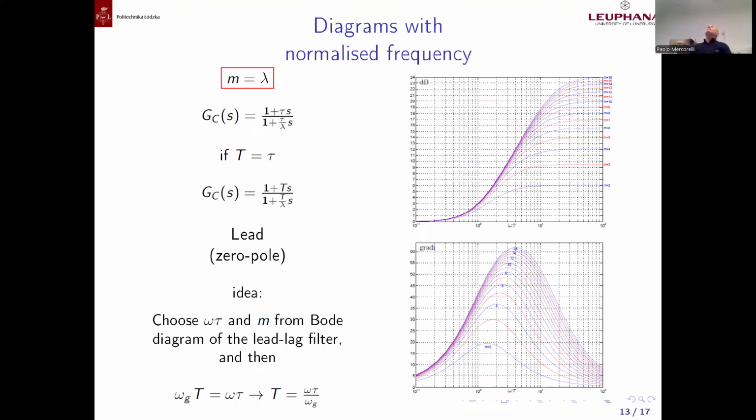the guarantees over time. This is again the concept which I told you this morning, because in the complex analysis, we freeze the time. Of course, the assumption is the system must be stable. This means the steady state should be achievable. This means the poles must all have negative real part, and just a single pole on the imaginary axis, because otherwise the system is unstable.